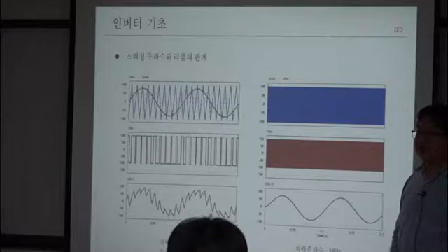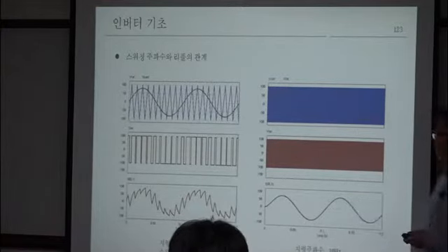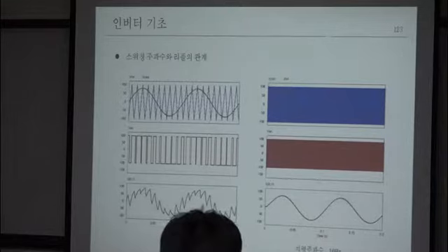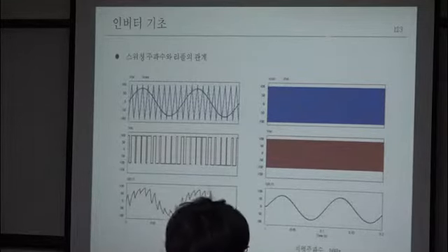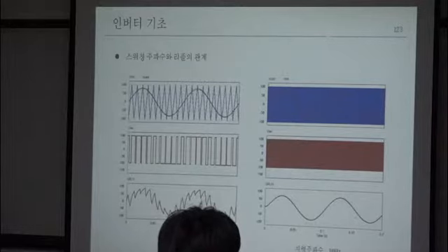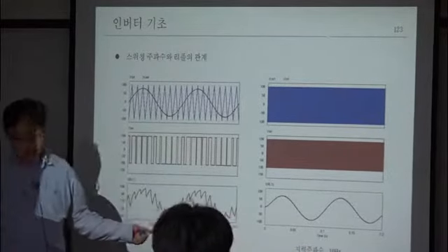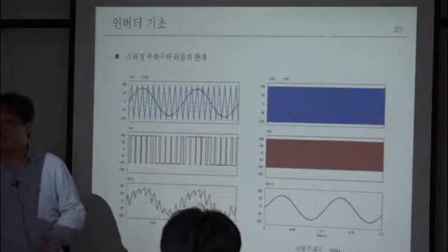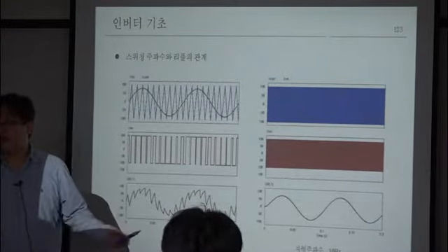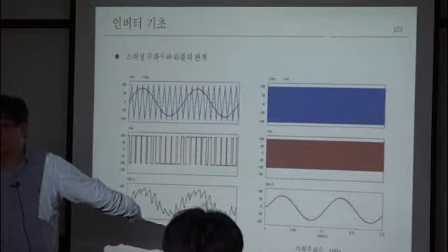Also, consider your magnetic component, like the inductor. The inductor also has loss. You know that in this curve and this region, the frequency of this movement is also very high. Then it also creates additional loss. So implementing high frequency is very important to make a compact power conversion system, but it also has limitations according to the switching loss. Okay.